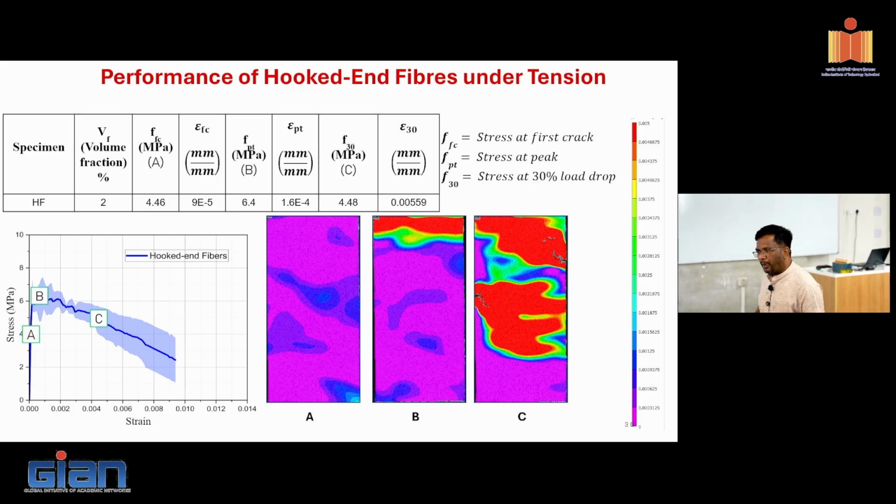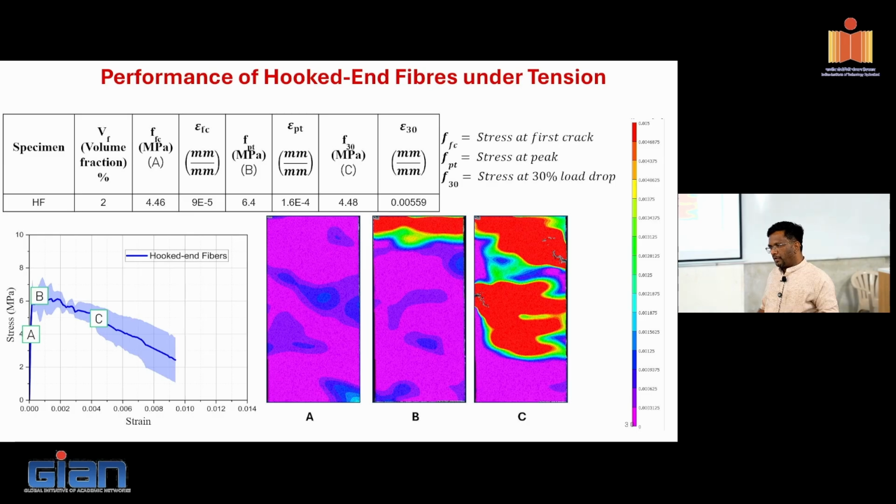So again, we are looking at what could be the reasons why. I have one question. Please. Earlier, for the direct compression, you said for UHPC there is a sudden drop. In one graph you had shown the parabolic, plastic, there is a sudden drop. Yeah. But in direct tension, they have a much more gradual drop. Correct, yeah. Why the sharp drop in direct compression?